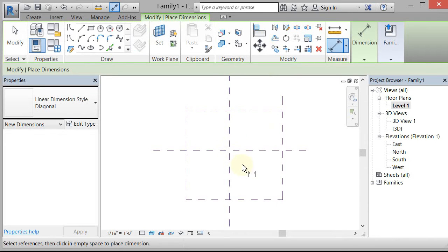So I'm going to left click on that, left click on the center one, and then left click on the right reference plane and kind of pull it up, and then I'm going to left click on nothing. And I'm going to hit the equals. So basically it's going to equal those reference planes out around this, so it'll always have the same distance between them.